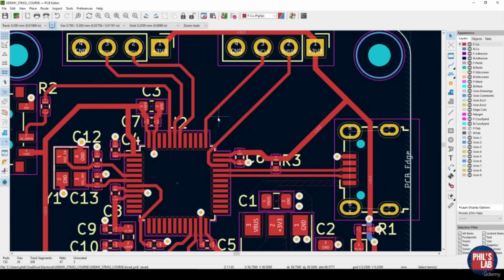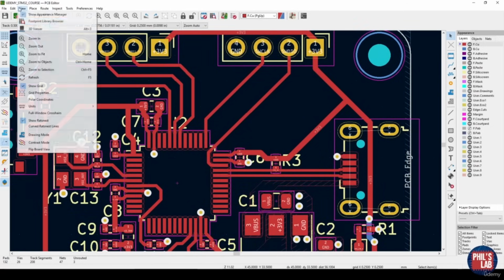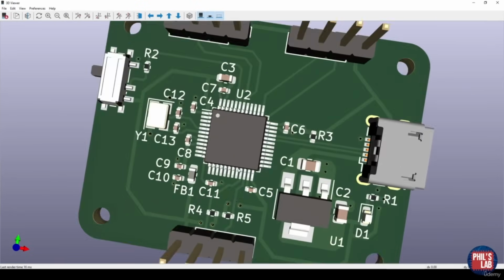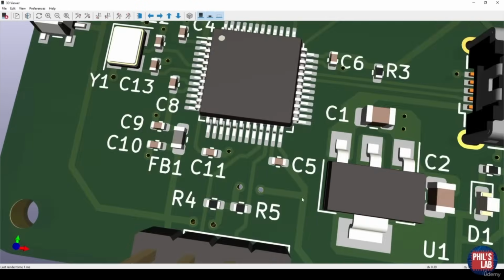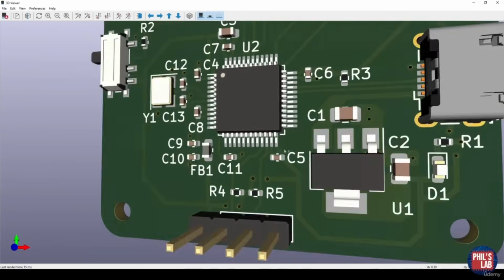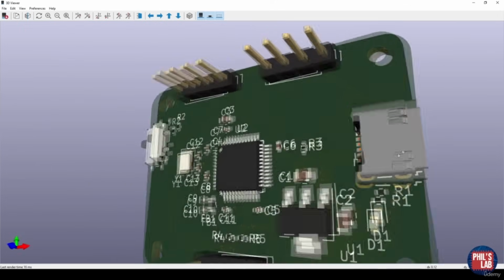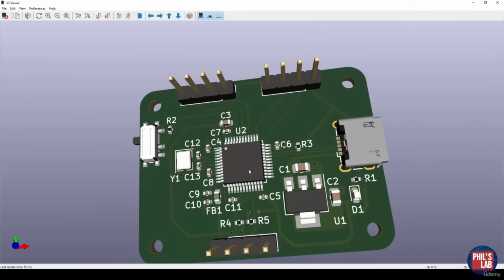Once you're done, press B again to re-pour, and then check everything out in the 3D viewer, like so. And you can see, also right-angled corners are absolutely fine, and don't let people tell you otherwise. And there we go. So there we've finished our very crude routing and layout of a very simple PCB. And if we ship this off now, producing the manufacturing files, this would work.